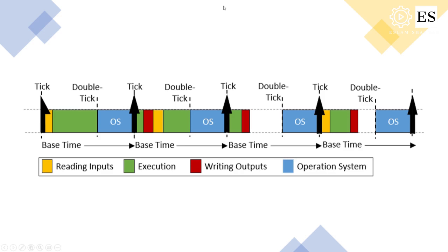For simplification, let's assume the CPU has a timer with a base time that varies from 1 millisecond to 50 microseconds. That base time is the time frame for a constant interrupt where a scheduler buzzes Windows and provides time for TwinCAT real-time tasks.